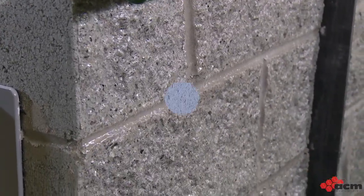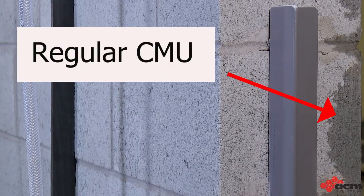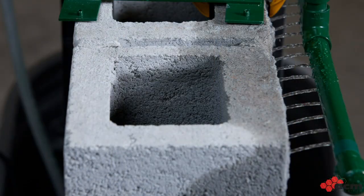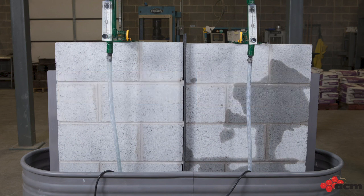Rainfall is simulated with a spray bar. As you can see, within a fairly short space of time, the regular unit absorbs water at the face shell surface. This water is then wicked through into the cores and all the way through to the back shell. After 4 hours, if we take a look at the back of the demo wall, we can see the difference. The water repellent wall does not absorb water, even after 4 hours of continuous spray.